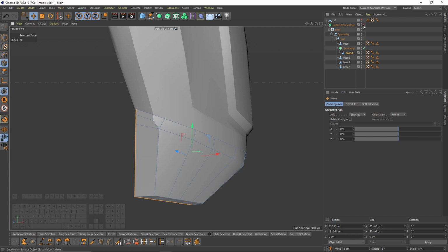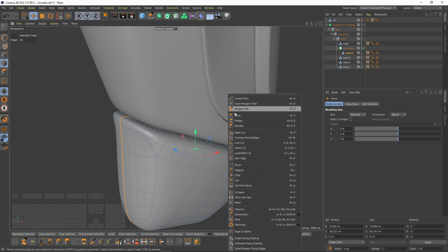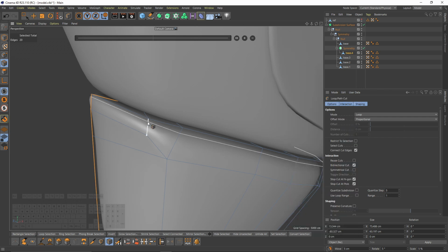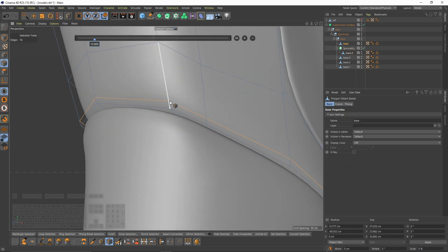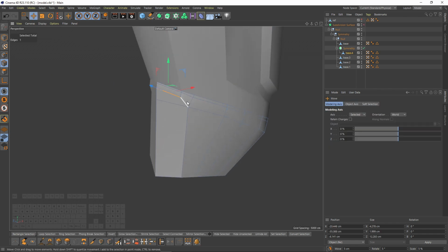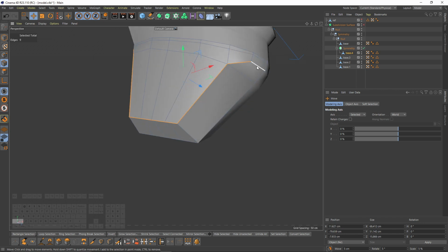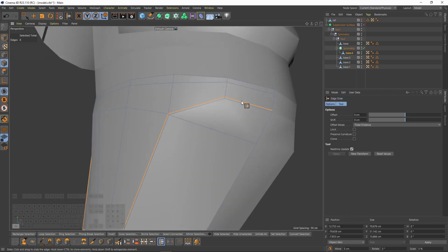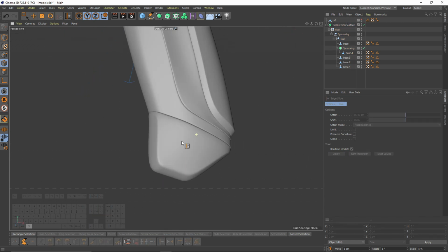Okay, let's enable subdivision surface. So first thing, we need supporting edges. So let's quickly add them. Right click, select loop cut, and one here and one for the inside, and also for the base. And I will add these supporting edges too, but for that I will select these edges, then right click, select slide, then press Ctrl and slide. Perfect.